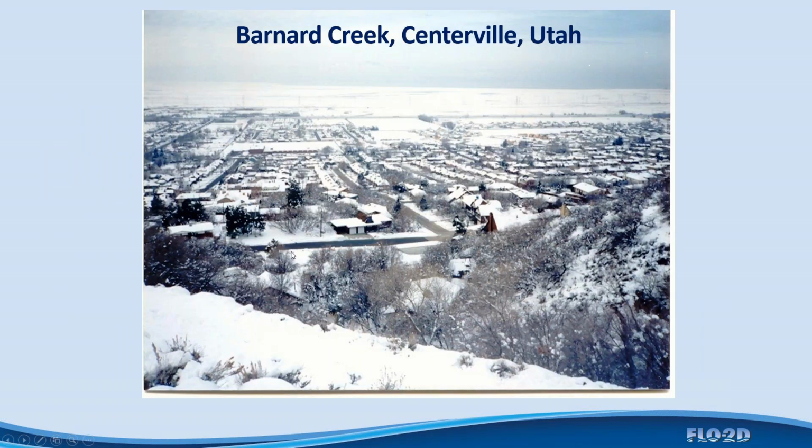I'll give you a very simple example of one. This is Centerville, Utah. I think they built an actual mud debris flow basin in here at some point. They used to have a little detention basin here, which didn't store anything, not even a percent or two of the 10-year event. So this comes down, the frontal wave hits it, puts a little debris in it, it just overtops it, runs down the street, gets in amongst the houses, and comes down this street pretty quickly, and smacks right into this school building.